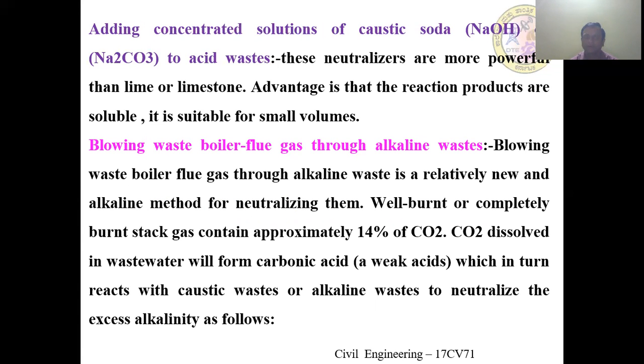Another method is adding a concentrated solution of caustic soda to acid waste. These neutralizers are more powerful than limestone or lime. The advantage is that the reaction products are soluble and easily handled, suitable for small volumes. So this is very powerful. Sodium hydroxide or sodium carbonate is very effective in neutralizing an acid.